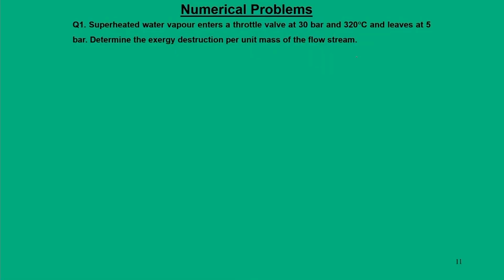So, you all know that a throttle valve is a valve which regulates the flow conditions entering a system or medium, and through this throttling process, the thermodynamic parameter that remains constant is enthalpy. So, here the problem given is that we have a throttle valve kept in a medium. The valve opens and closes. Some steam is entering, which is superheated water vapor.